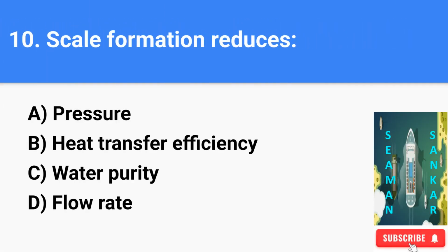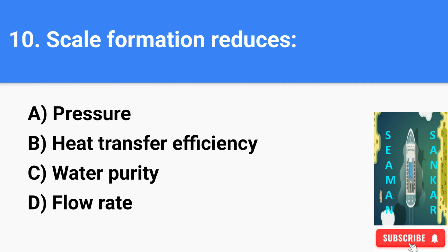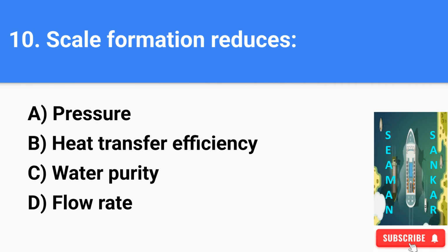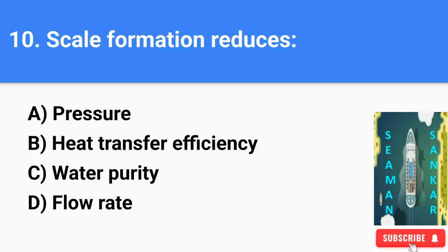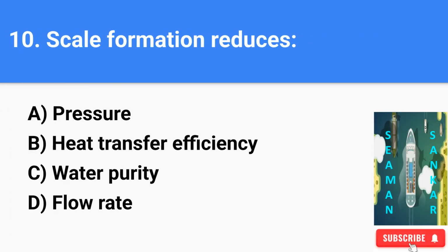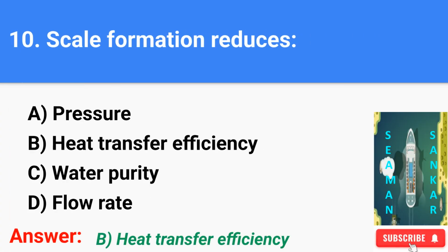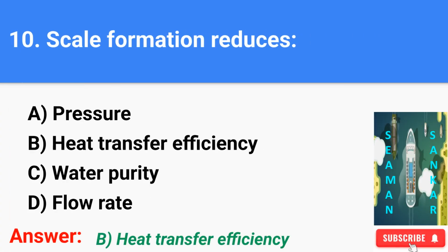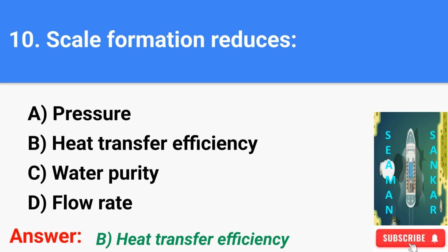Question 10. Scale formation reduces A. Pressure, B. Heat transfer efficiency, C. Water purity, or D. Flow rate. The answer is B. Heat transfer efficiency. Scale acts as an insulator, significantly impeding heat exchange.